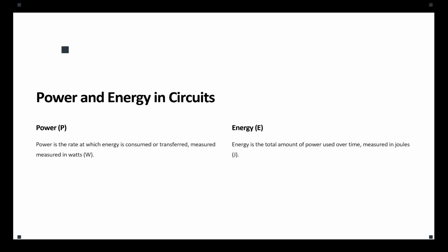So when you want to design or test or choose a component to put in your circuit, you need to pay attention that you do not exceed the nominal power of that component. For example, in this lab, you are going to place some resistor and you are going to supply some energy from your DC voltage source, meaning you're applying a voltage and you're conducting some amount of current through that resistor. That voltage times current means you are actually injecting a certain amount of power into that resistor.